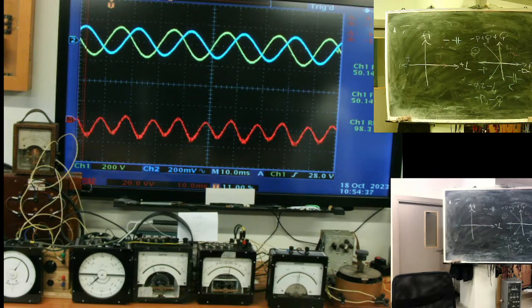negative, let's say negative direction, to suck reactive power from the network. To prevent overvoltages, these generators are equipped with such an excitement system, so it's normal for them to work in reactive power consumption or diminishing mode as an anti-capacitor.